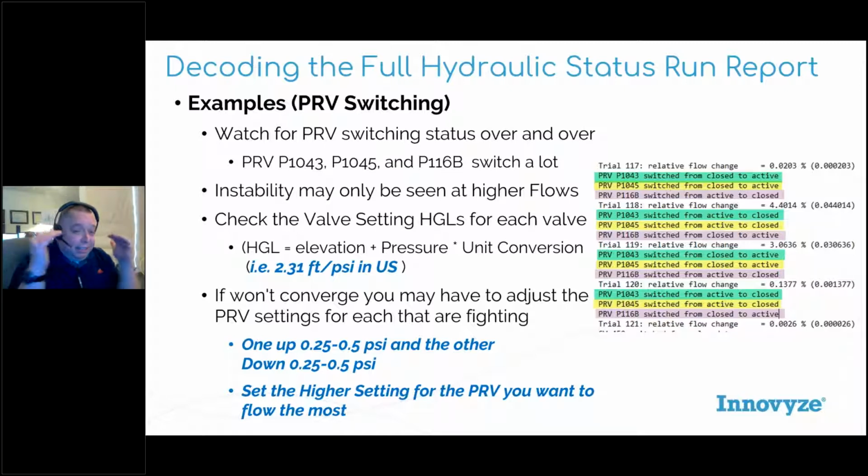Ideally, if I could get centerline elevations for my PRVs, that's ideal. But if you can't, there's definitely some uncertainty in the elevations I've got there. And when they go out and set these, they're usually putting a manual pressure gauge on them, so your settings are at best probably plus or minus half a PSI anyway. So adjusting these a little bit is pretty defendable, it's not too big of a deal, but just be aware of that.